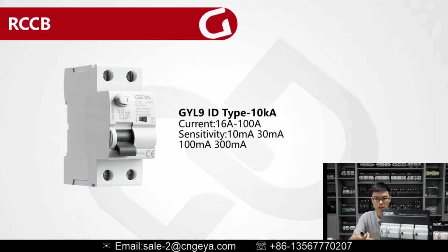Because it is with better quality, the current we can do is in a wider range. This one we can do from 16 amperes to 100 amperes. And for the sensitivity, we also have 4 different options. We have 10 milliamperes, 30 milliamperes, 100 milliamperes, and 300 milliamperes.